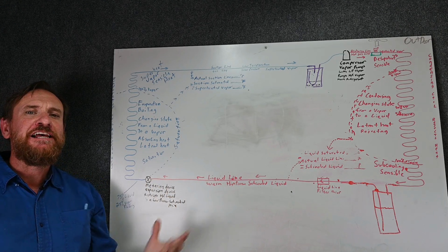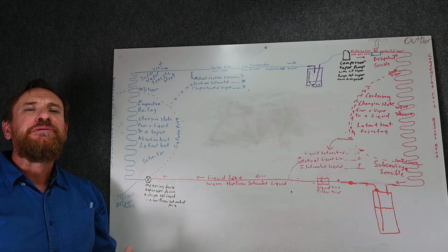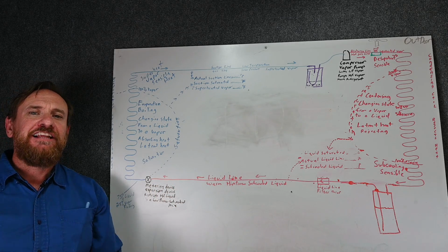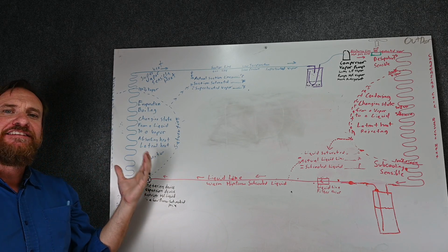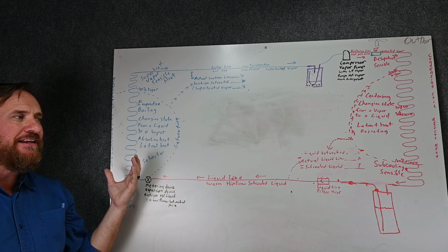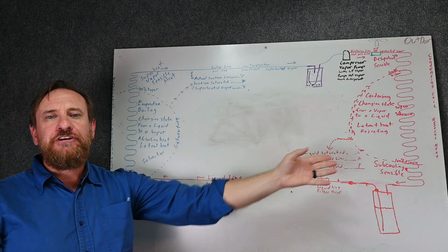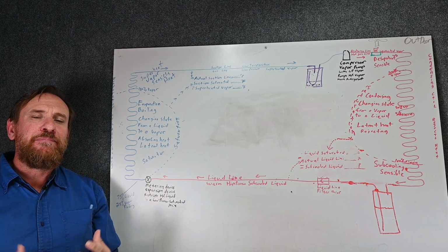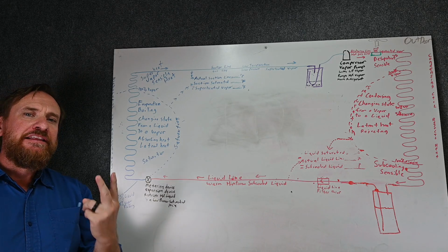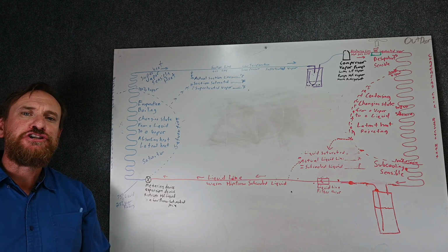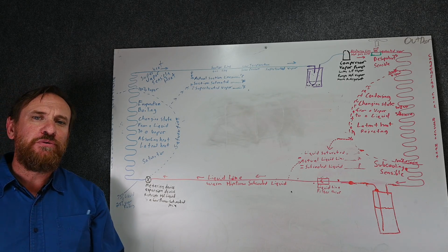A lot of people take those laboratory conditions and try to apply them to a varying lifestyle. Even if you had a customer that could maintain a set indoor temperature and humidity, the outdoor temperature is still changing. So having these set pressures is just not practical. The second way of knowing what your suction pressure should be is an app called MeasureQuick.